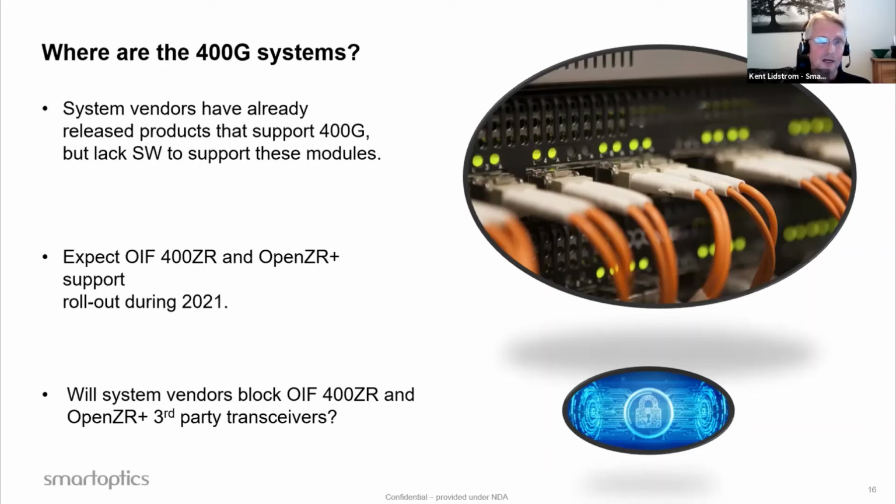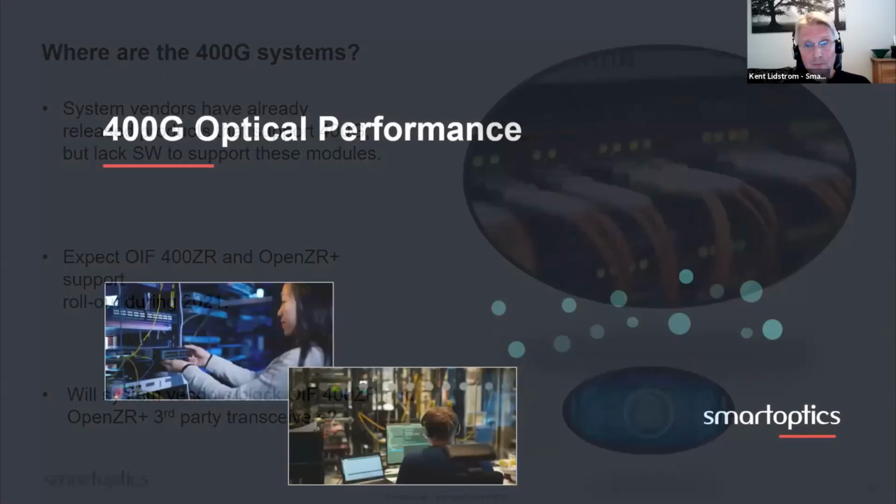So next time we set the wavelength in an external box and plug it back into the switch or router, it remains with that wavelength. So you have to pre-tune it before you plug it in. Once that switch or router vendor adds support for it, that will not be necessary anymore. But right now, that's where we are today. So we may or may not need to do a small manipulation in order to get it to work. So that's pretty much where we are.